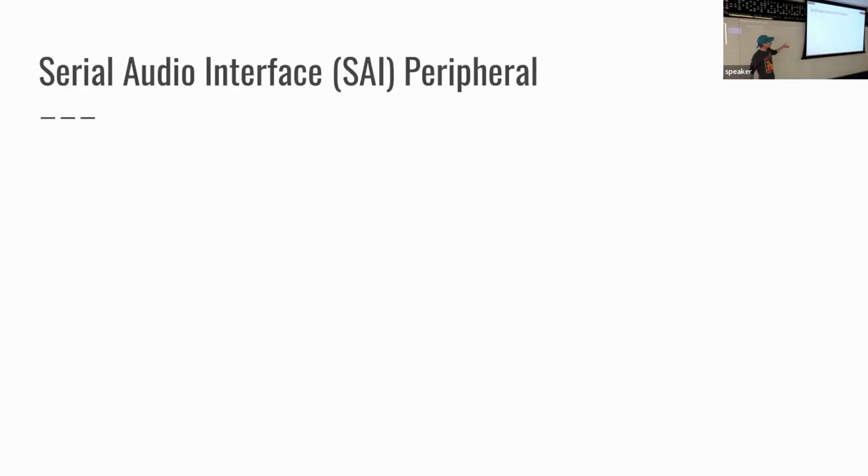So the peripheral that can deliver this I2S digital audio data is the SAI, serial audio interface. That's a good term for grepping through documentation. But even if you're in Linux land and you want to know the driver for audio on your platform, if you search serial audio interface or SAI, it'll take you right to it.